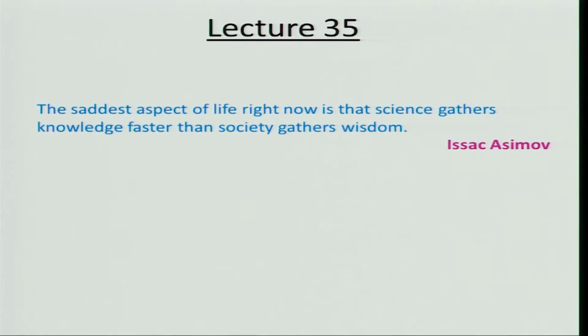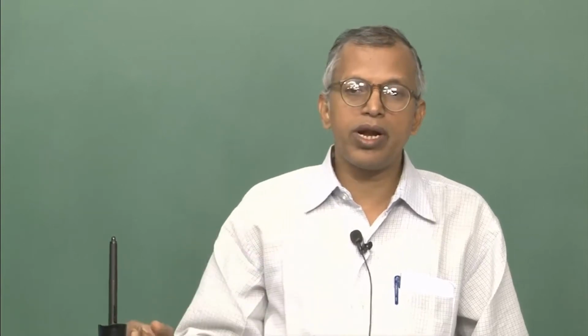Let us recall what we learned in the last lecture. Last lecture, we looked at the analysis of turbofan engines, and then we looked at the parametric characteristics of the turbofan engines. We learnt that the bypass ratio and the fan pressure ratio and compressor pressure ratio play a very important role, and by enhancing the bypass ratio we can reduce the TSFC.